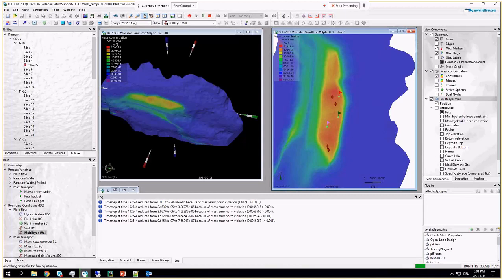Okay, Stefan, do the newly formulated discrete feature elements allow one to simulate pipelines carrying mine water from wells to some other locations in the model? I guess you mean here a closed pipe, no? Yeah, you have this option of arbitrary path, node path, which basically allows only exchange of fluid, mass, and heat at the beginning and the end of the pipeline. Whatever happens in between, there is no outflow. I hope this answered your question, Javier.